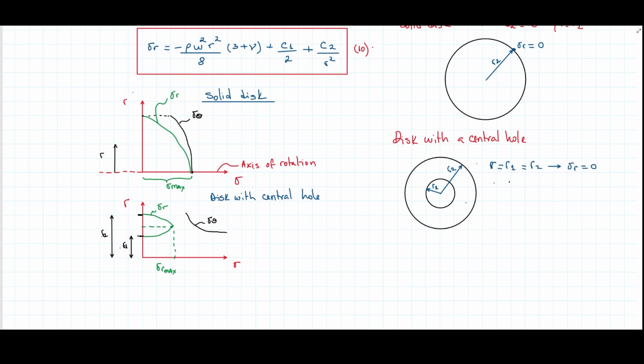If I know that these stresses vary along the radius, like in the application with a central hole, which is pretty similar to the video we saw at the beginning of the lecture, where the disk exploded or disintegrated by the high angular velocity, then you see that the circumferential stresses are way larger, meaning that we could use certain failure theory to determine if that's going to fail or not.